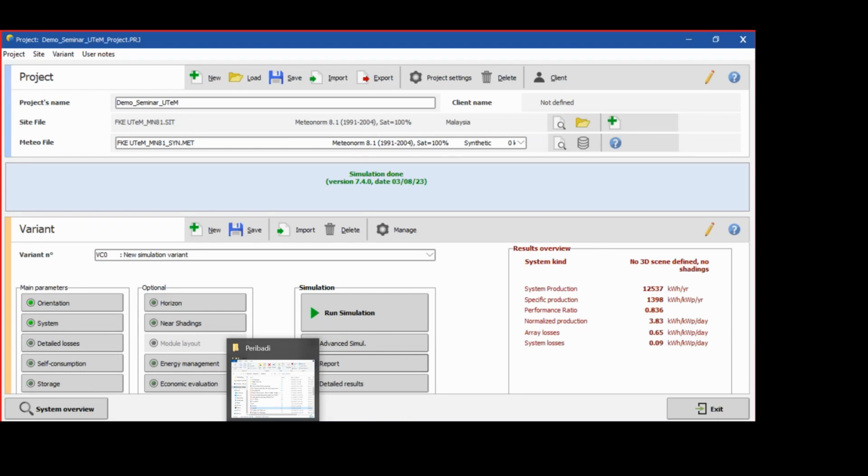If we use two MPPTs and both systems are facing the same direction, then they are going to track the same power. Right. So the next one: in a PV system, can we put different panels on a different MPPT of the same inverter? Different panels, yes, can. Like I said, different MPPTs are like having two separate inverters combined together. So you can put different panels.